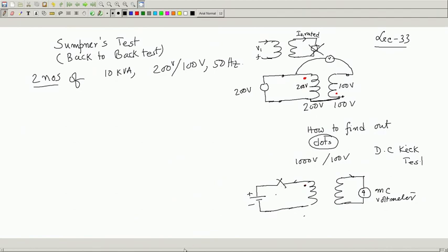The moment you close the switch, it is not an AC supply, but there will be a sudden change in flux. Therefore, we expect there will be instantaneously an induced voltage. And if this happens to be dot, and see, moving coil meters have plus minus marking, is it not? If current enters, it gives positive. So, a zero centered meter you take, zero centered meter.